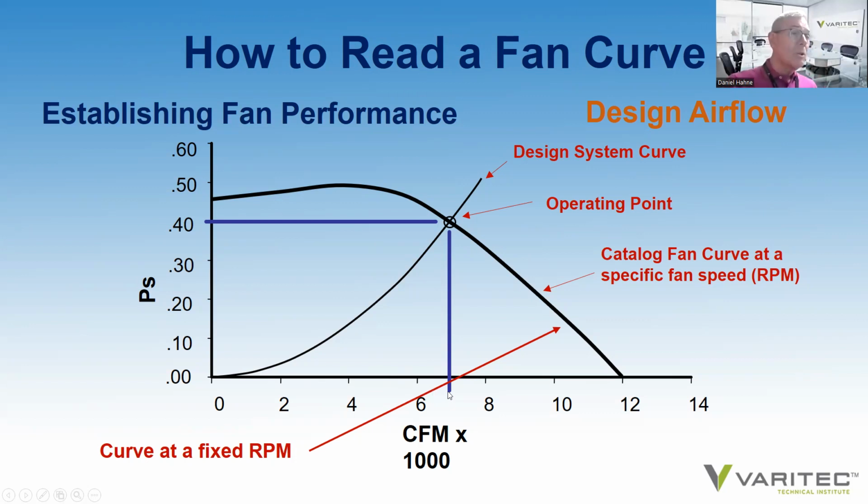The reverse is also true. If we have a fan wheel with certified data and we know we're getting this much CFM, if we look for the point of intersection with the fan curve, we can then calculate the static pressure drop in the system.